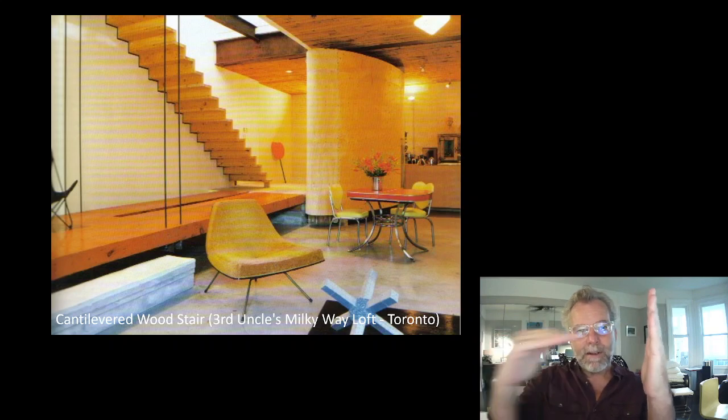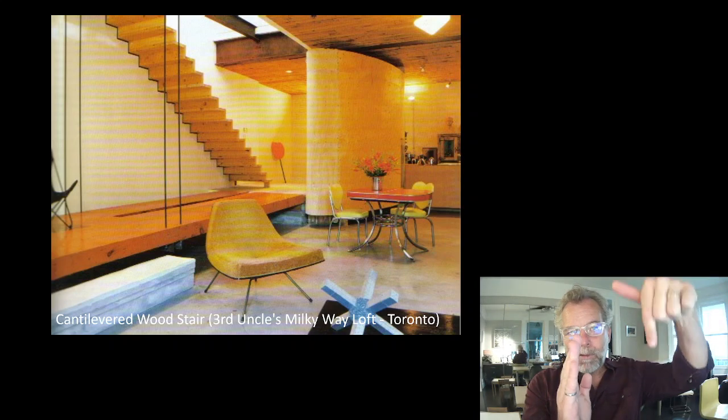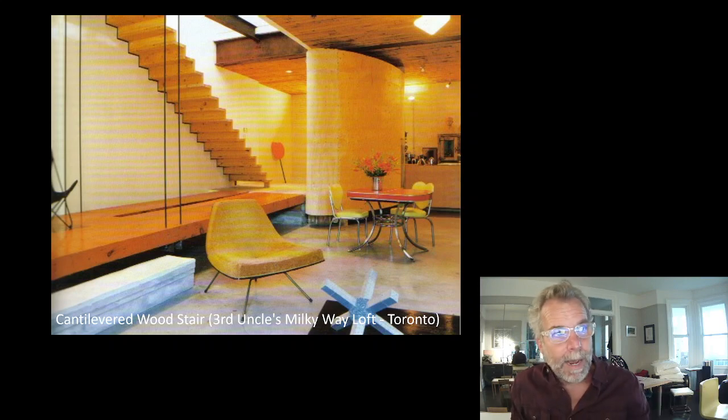So we cantilever out the stair, we prop it on the stud wall, and we use the block to hold down the back span. So what we're doing is cantilevering through a double wall here. It worked well. They were very happy with it, and we never got any callback or any complaint. I think because it was reclaimed lumber.